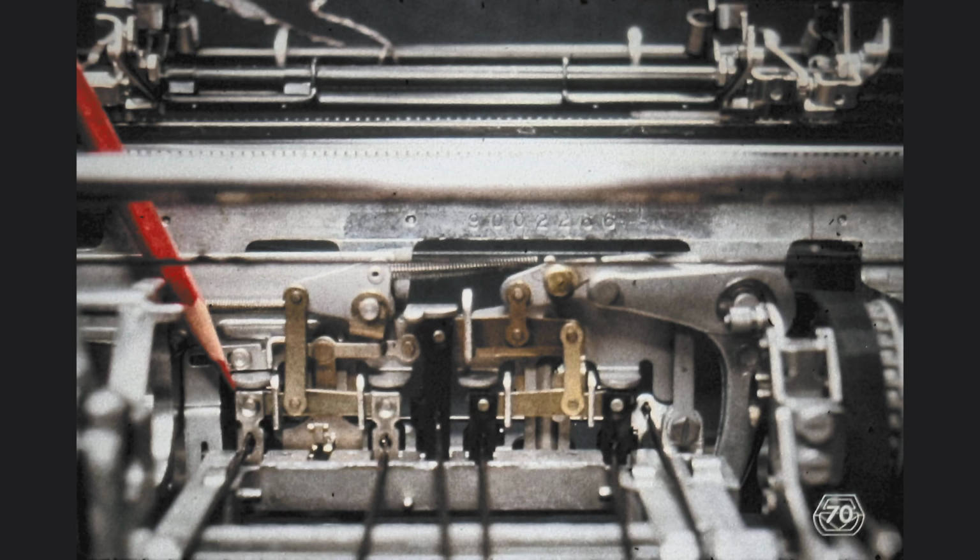Considering that the link which connects the horizontal tilt differential lever to the tilt bell crank is positioned at a distance of 2/3 of the lever length away from the pivot point of the lever, the amount of motion obtained from the tilt 2 latch, when it is pulled down by the cam follower, is reduced to 2/3 of the total value by the time it is transferred to the tilt bell crank.